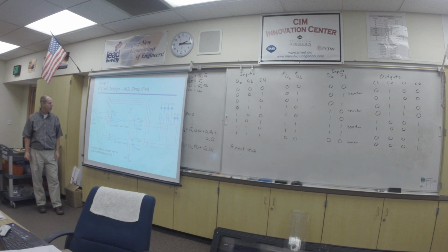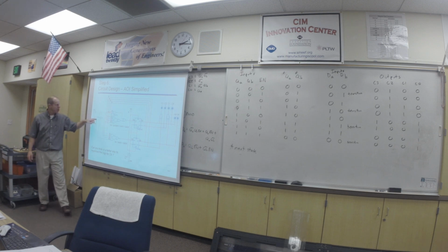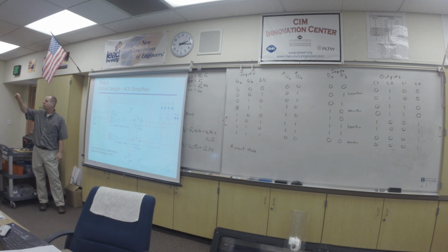So we can get those over there. So here's our one switch to do the whole thing. When is this going to cycle through? Every time enable is high. I go to enable is high, and it'll start cycling through. When I go low with the enable, everything stops. It holds on whatever number that we've done.